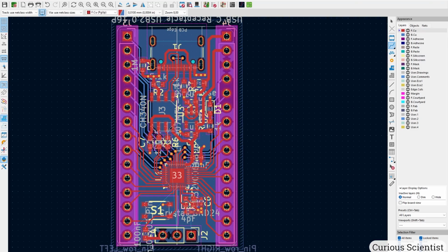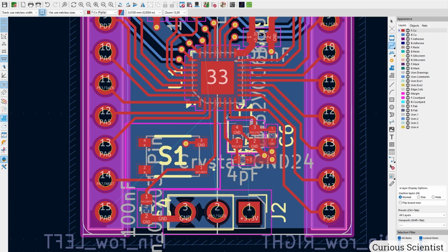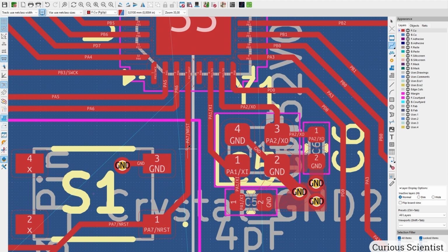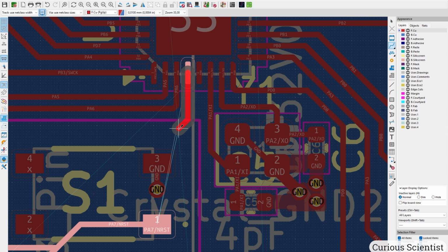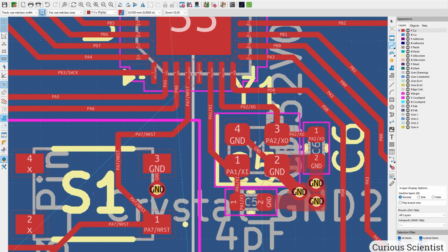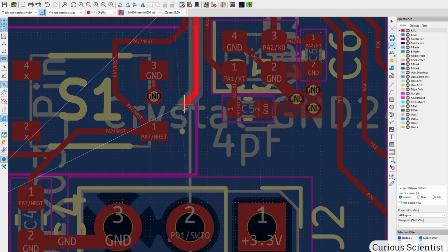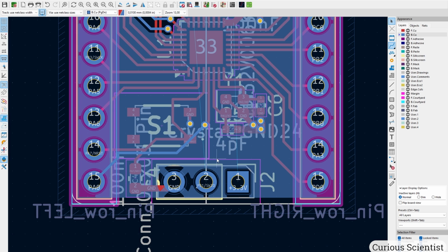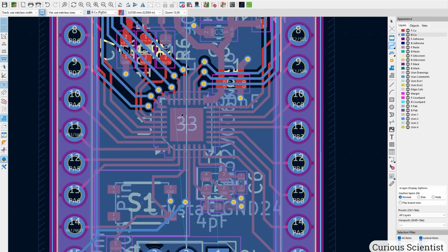So this is how it looks now, and just a few pins are missing. How I can mitigate that is that I can do a funny thing here. I actually just remove this trace. I move this in between the pins here, and then now it's easier to route this one in a bit of a funny way, and then this has to go underneath. And then the SWIO has to be solved as well.